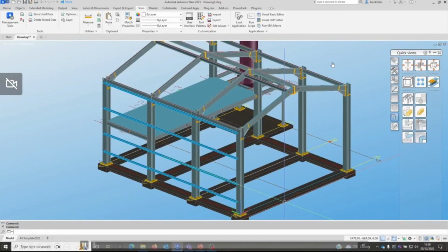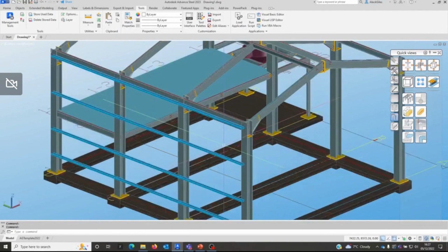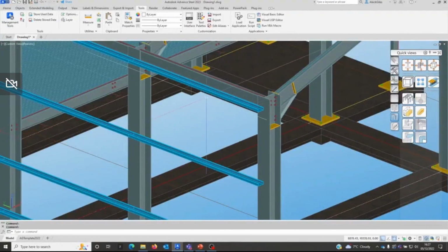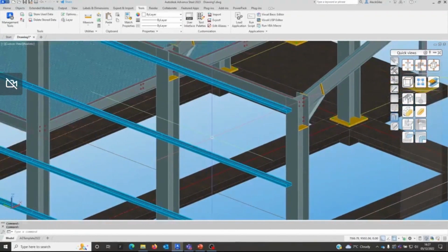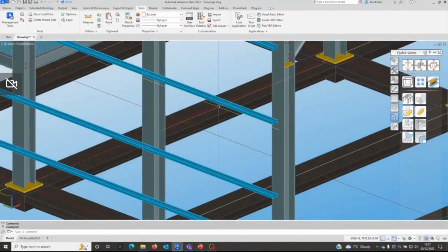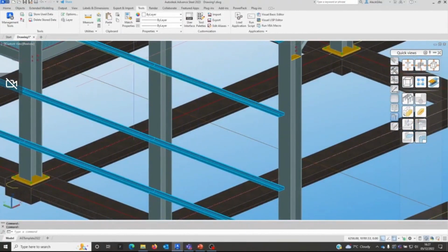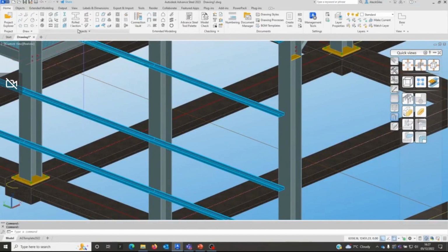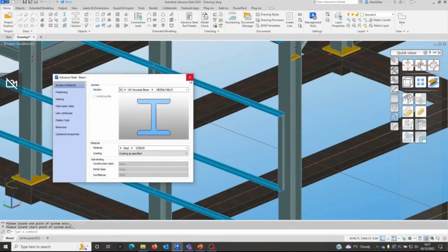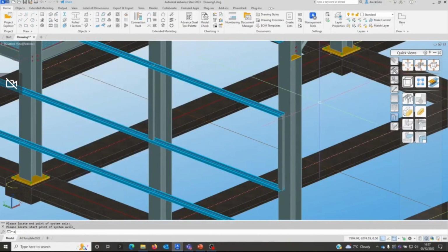Sometimes when you're modelling in Advanced Steel, you want to add more members that are matching existing members in the model. But it may be some time since you put those existing members in there. For example, in this model I have some cold rolled side rails here, and I want to add some vertical members for window opening in the same area. Now I could look up, double click on the rail to see what size it is, but another alternative is to simply draw two beams of any old size, don't care about any properties there, let's move them to the right places.